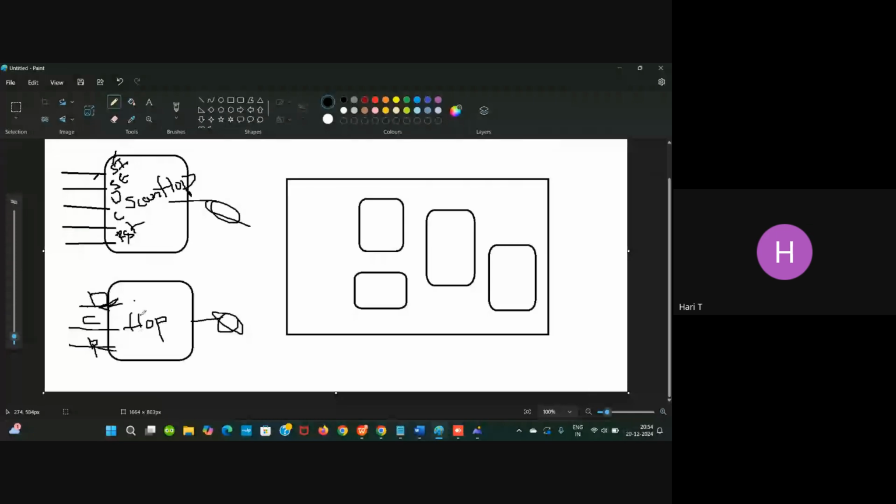And after scan insertion, every D flip-flop will be turned into a scan flip-flop, and every flop will have controllability in terms of DFT. See, these 2 pins come under DFT pins. These 2 pins will take control of your entire design.